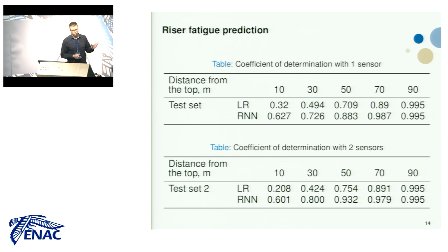We solve the riser equations using the finite element methods, and we generate a data set which shows us the last 50 displacements and accelerations of the riser. And we compare how different machine learning models can predict the bending at the wellhead using one and two sensors placed in different places. Here in the first table, we can see that compared with the Euler-Bernoulli beam, the linear regression, which is the first line, doesn't give a reliable prediction when we place the sensors in places convenient for maintenance.